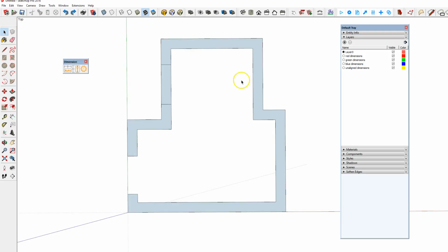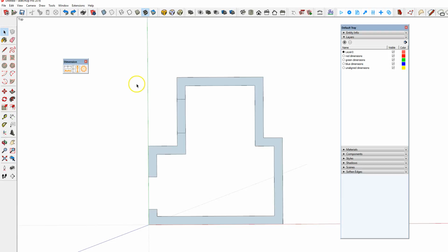So if I want to put on all my horizontal measurements or even vertical measurements, I just select the lines. Here at the moment I'm selecting the horizontals, but because I'm only clicking on the horizontal button, it'll only add on the horizontal measurements. So click on there and it adds those measurements all in there, and they're all offset at 300, or I think it's the last measurement I've typed in.